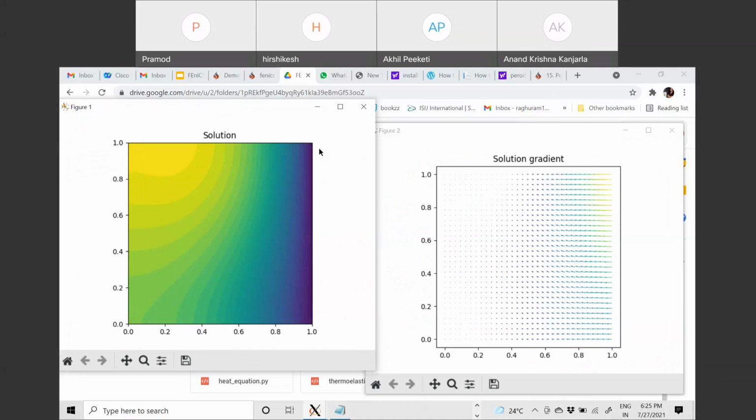In most simple cases, you can omit the relative tolerance. But in some cases where convergence is very hard to achieve, you might want to play around with those parameters: relative tolerance, and there is also something known as absolute tolerance, and then the number of iterations and all those things. It is assumed that you know a bit of Newton-Raphson. In that case, the relative tolerance would have been clear. I hope I have answered, or at least given you the direction, and I can get back to you later on.